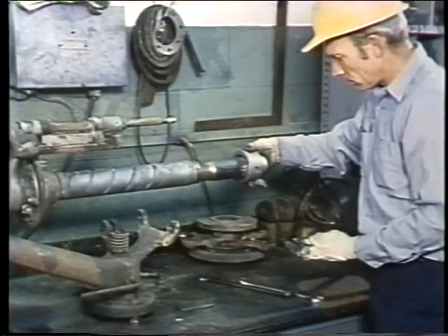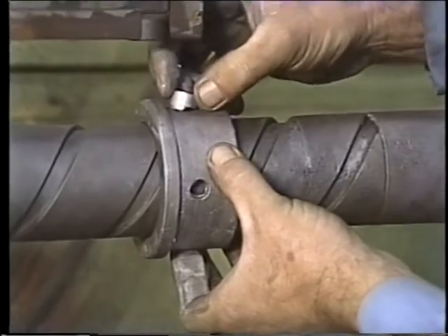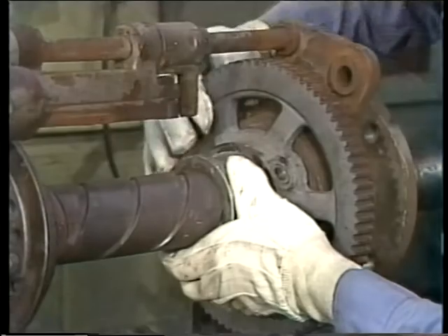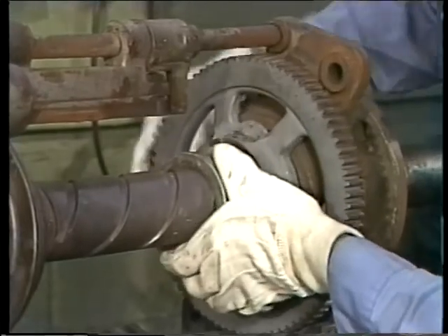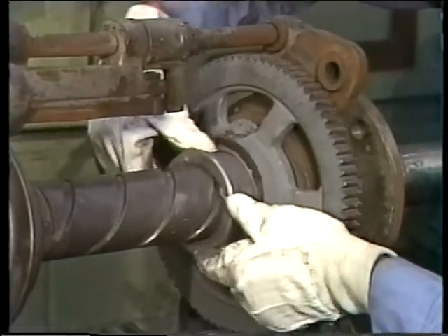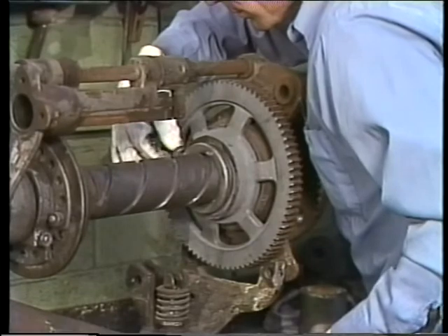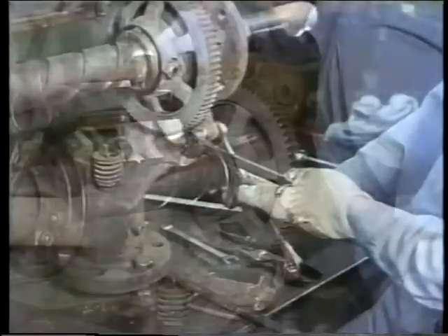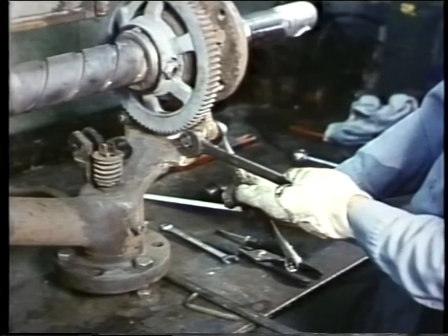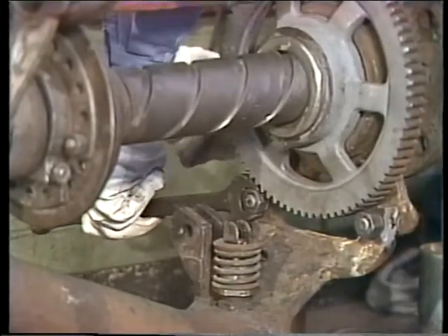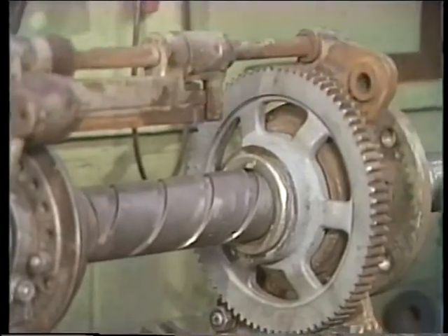The element's drive collar is fitted over the element, and the 2 collets are dropped into place in the collar. Now comes the main drive gear and the front mount of the soot blower. The drive gear has to slide over the collar and hold the collets in place. In order to find the tapped hole for the set screw, it's convenient to use a drift and then screw in the set screw and its lock nut. The front mount is bolted to the main casting and the upper guide rail.